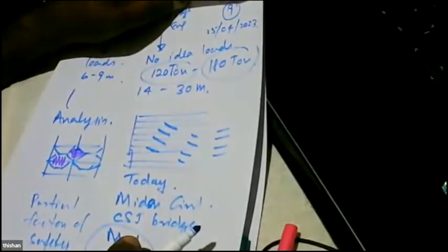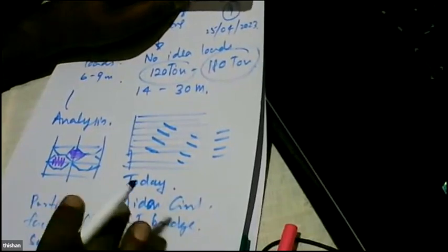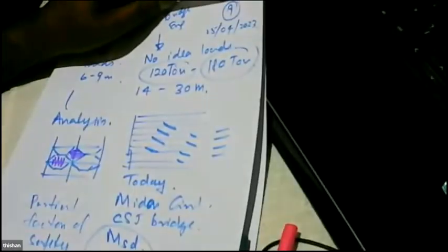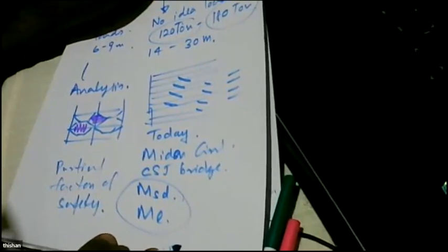These are huge loads. Already we start with a huge load and then we apply factors of safety. So a minor inaccuracy in the bending moment is not going to cause any problem to the bridge. So the moment you get that attitude, you'll find that bridges also can be designed pretty easily, but you have to be very concerned about the foundation.